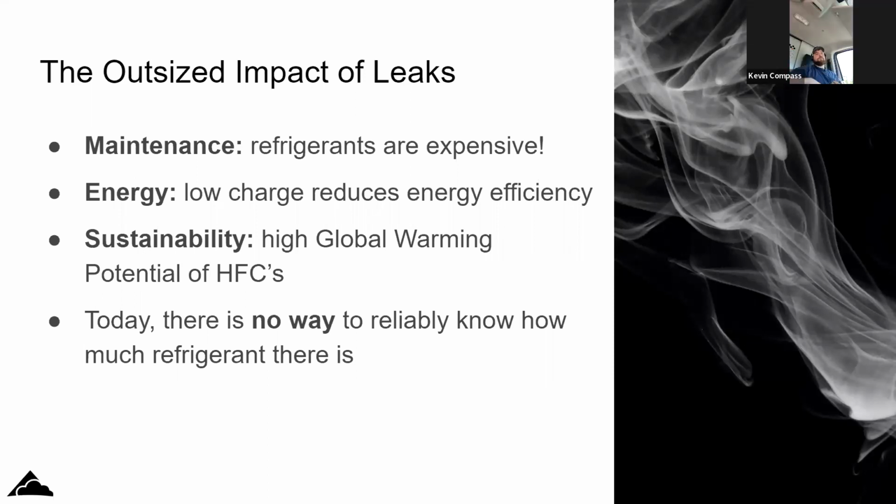Yeah, almost exactly. Leak checking is almost 100% a state of mind. If you're not patient and you're rushing through it... One big thing I've always taught guys is, just because you find a decent-sized leak, don't stop there. I don't know how many times I've seen guys find a pretty good-sized leak that could easily leak 100 pounds in a week or two, and then they miss another giant leak or another decent-sized leak. Then they're back a month later with another low receiver level or a low refrigerant condition.